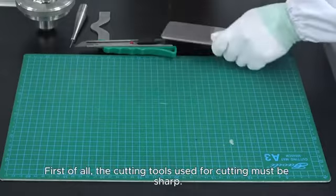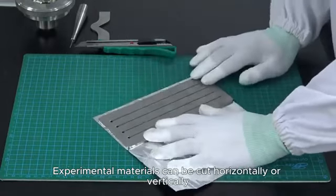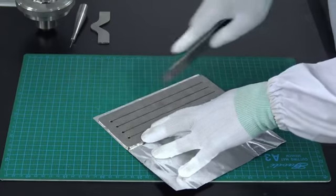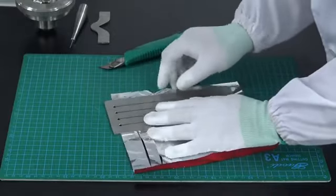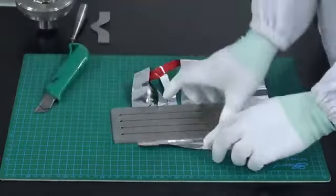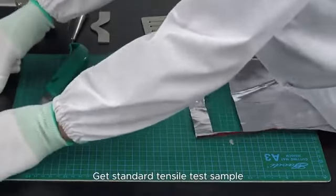Experimental sample cutting. First of all, the cutting tools used for cutting must be sharp. The edges of the cut sample should be smooth and without chips or burrs. Experimental materials can be cut horizontally or vertically. According to the requirements of your experiment, cut the sample. Get standard tensile test sample.